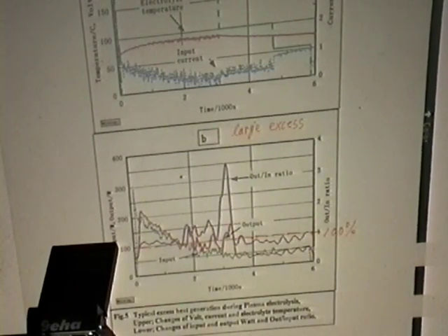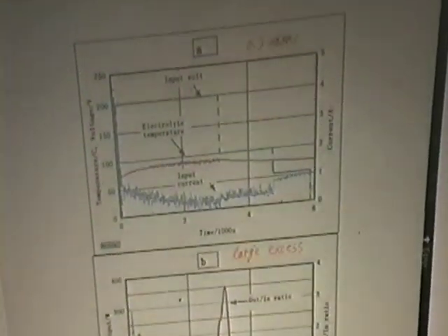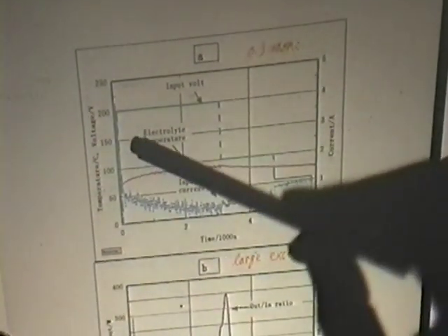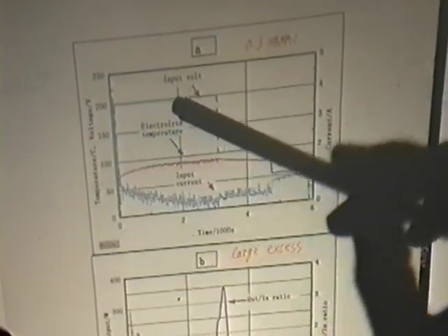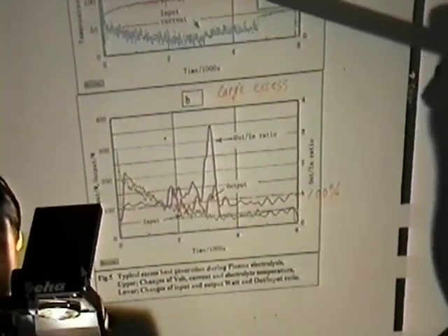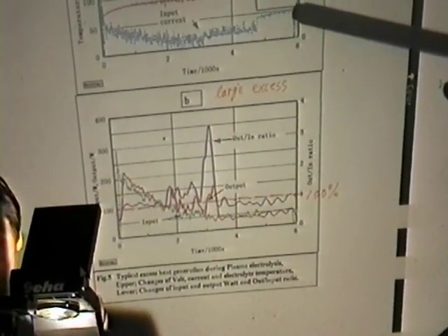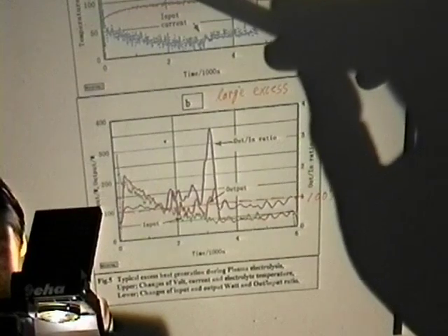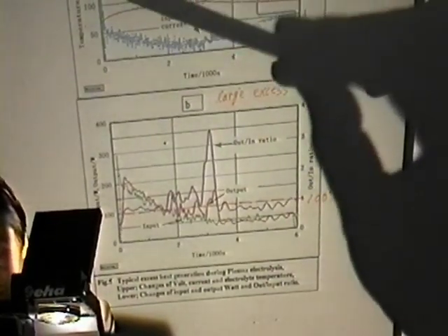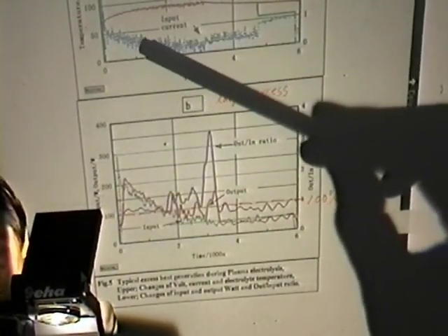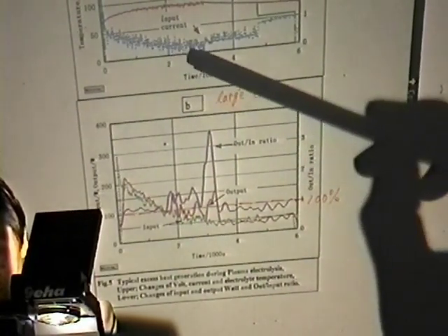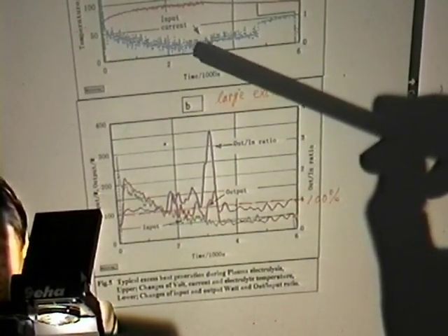And this shows another case of tungsten where the thickness was 0.3 millimeter. The output and the input ratio are changing with time. You can see this is input volt. I kept 200 volt and decreased to 100 volt and finally 60 volt. The current in the beginning was like that, 5 ampere, and decreased to almost under 1 ampere and like 0.5 amperes.